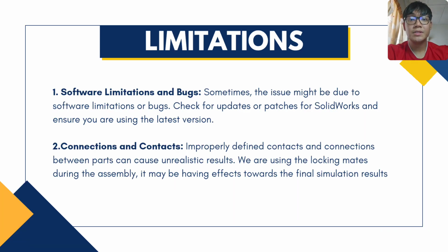To summarize, the simulation helped us evaluate the effects of different bar radii on stress, displacement, and strain. We found that increasing the radius significantly improves structural performance. However, some factors may affect accuracy, such as software limitations or locking mates used in the assembly, which might not perfectly represent real-world context. Ensuring proper connections and using the latest SolidWorks version can help reduce these issues in further